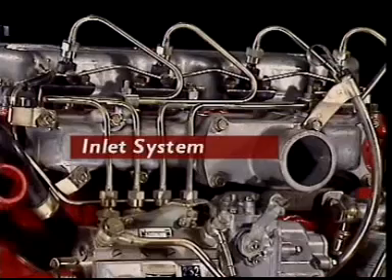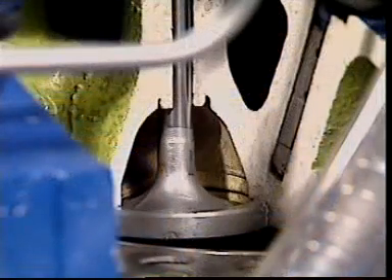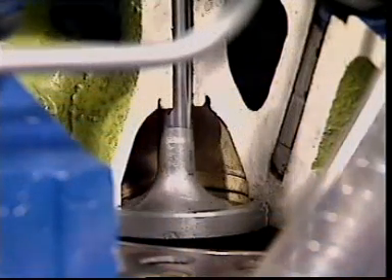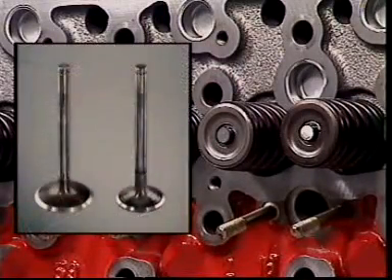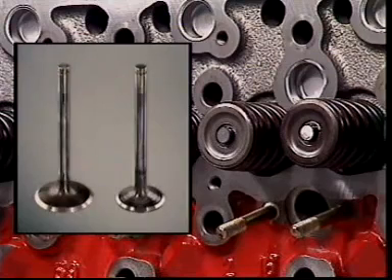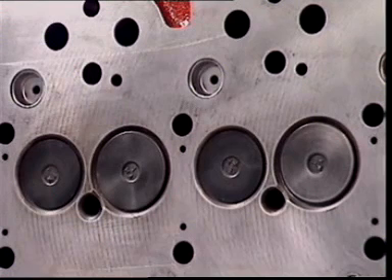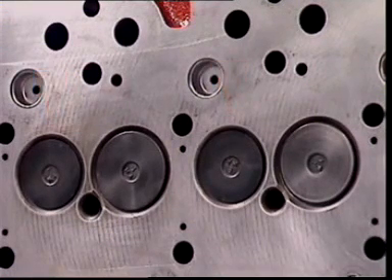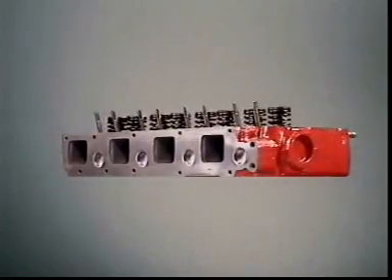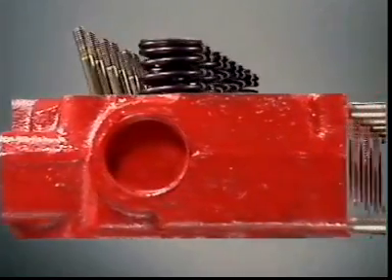In a four-stroke diesel, just as in a petrol engine, the inlet and exhaust ports are controlled by valves. But the much higher operating pressures and temperatures in diesel engines put more stress on diesel valves, which are usually larger than those in petrol engines. The intake valve passes only air, so it's cooler than the exhaust valve, which releases all the hot gases after combustion. Valves in the diesel engine are usually parallel to the centre line of the engine.